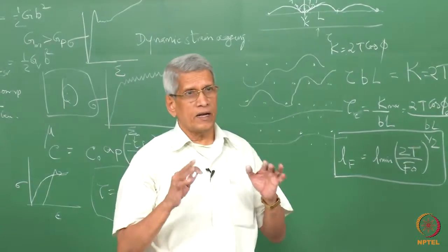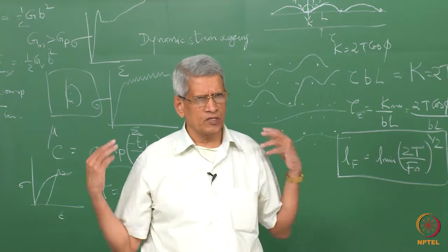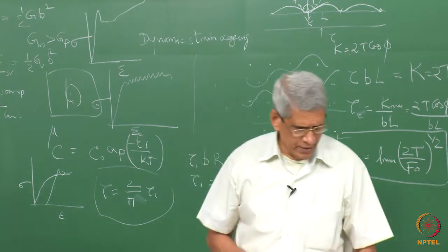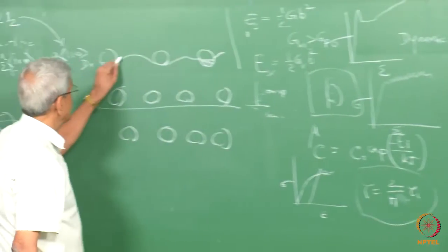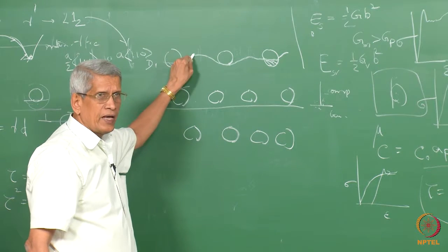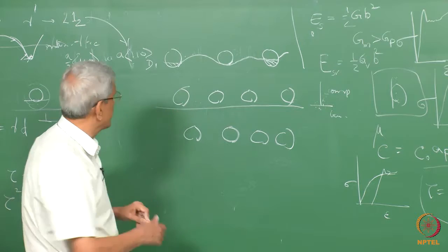It's seeing a disordered lattice. In a disordered lattice, if it doesn't see any obstacle, it will be a straight dislocation. And as this dislocation comes very close to it, since the Burgers vectors are the same and they are lying in the same slip plane, they will repel each other.